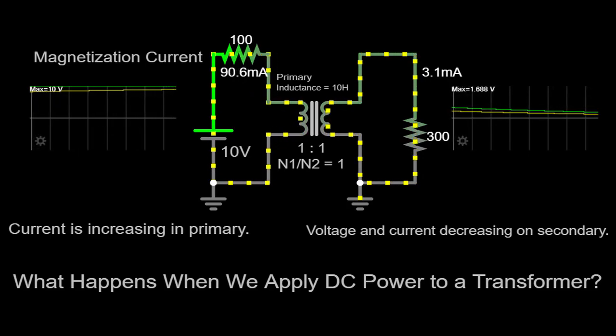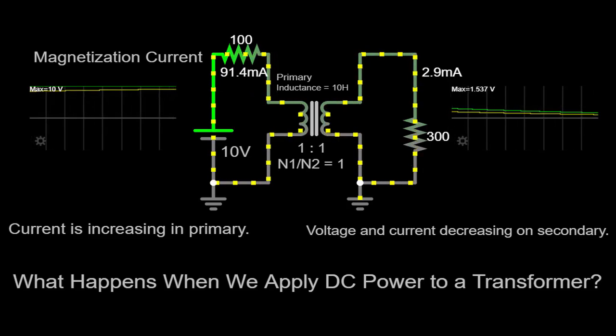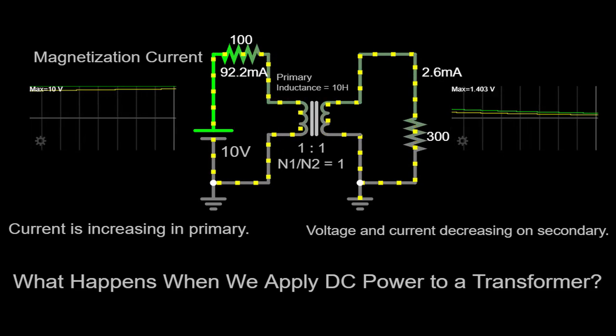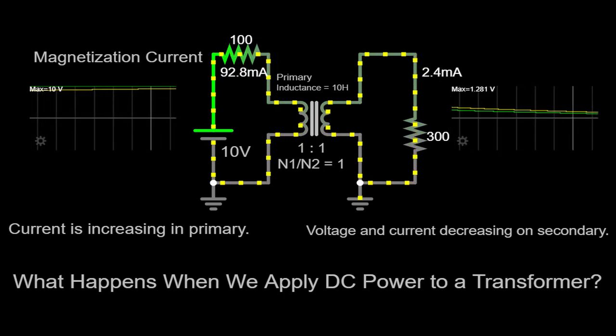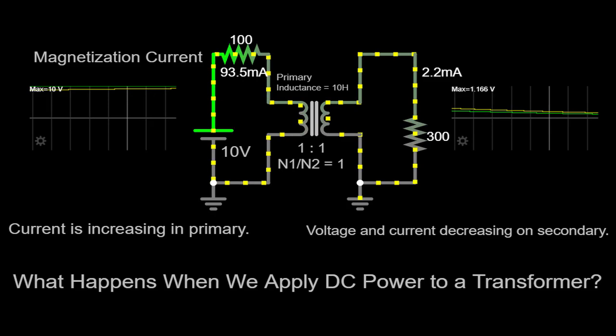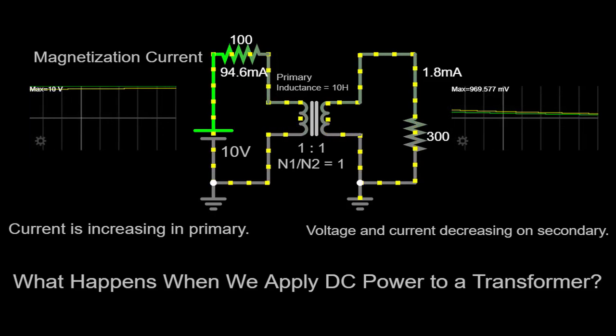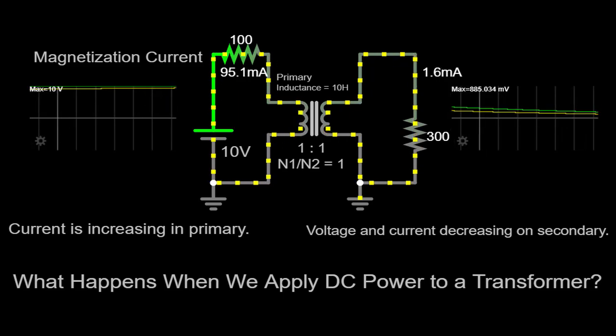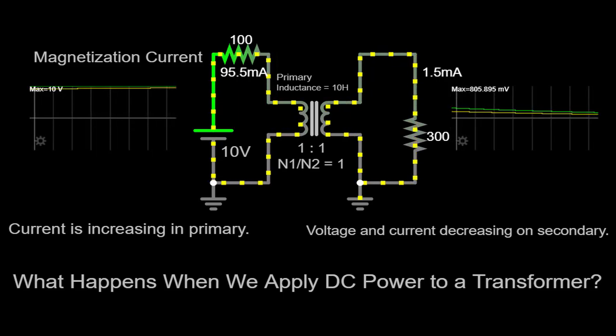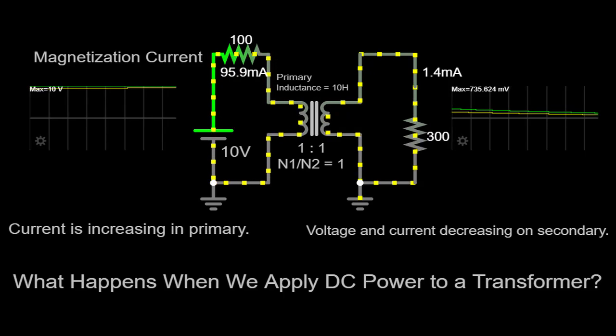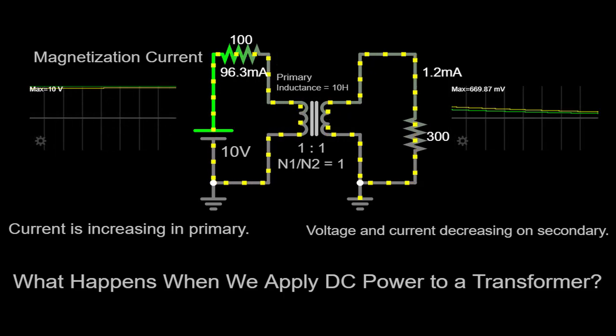The presence of DC in an isolation transformer can give rise to heightened heat generation, primarily due to core saturation. As the magnetic core reaches saturation and operates outside its intended parameters, excessive heat is produced. This increased heat poses a risk of damaging the insulation materials and other components of the transformer, potentially leading to